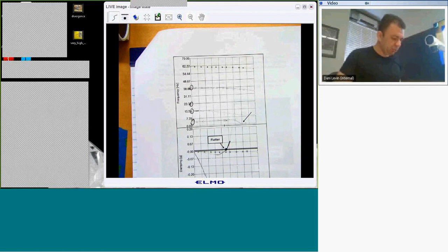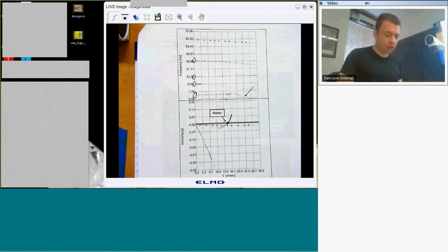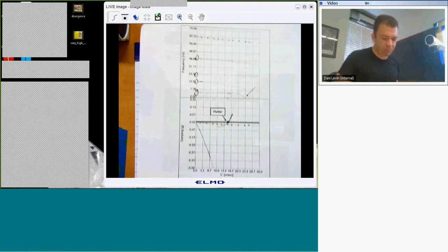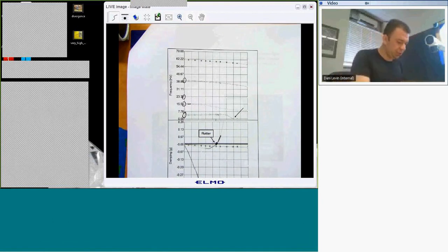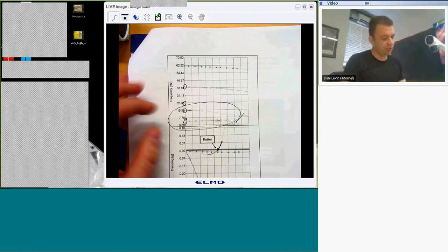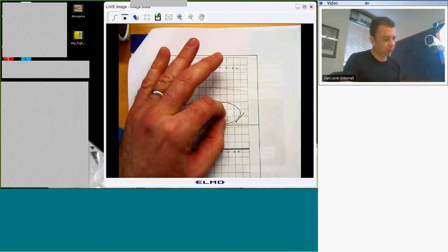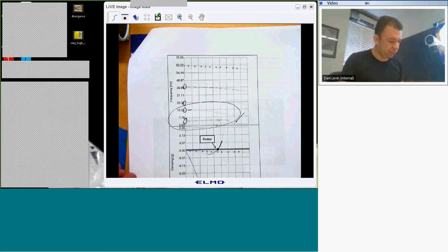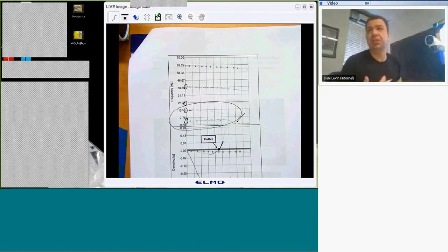Okay, so we go to the last part of this document. We're talking about instrumentation of this wing. My aim in this test is for you to see the two separate modes, which will combine into one flutter mode. If you remember from this document, the solution is flutter at around 12 hertz. 12 hertz is very nice because you can see it with your eye.